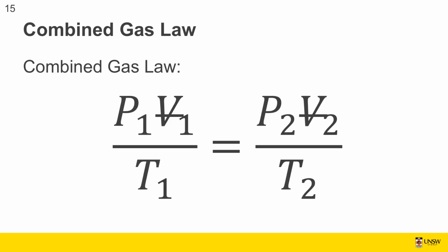But this is a consequence of, if you say that PV equals mRT, and you have a closed system, so there's no mass exiting the system or entering the system, then you can say that at state 1, P1 V1 equals m, which is a constant now, R, which is a constant, because you've got the same substance, T1. Bring the T underneath, and you can say that P1 V1 on T1 equals P2 V2 on T2. So you don't need to do the entire calculation every time. Is that self-evident?